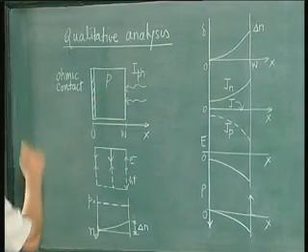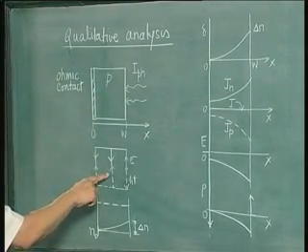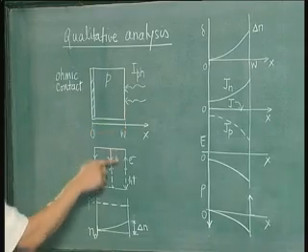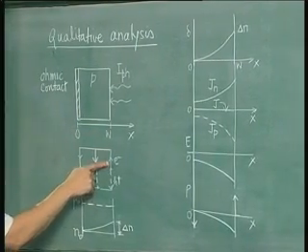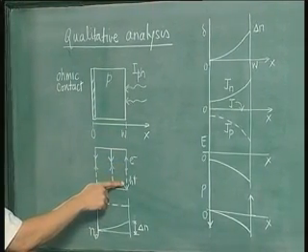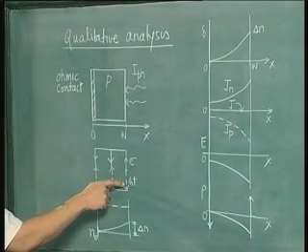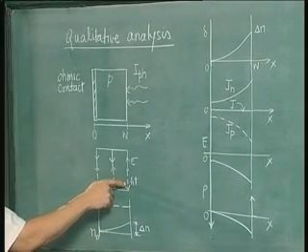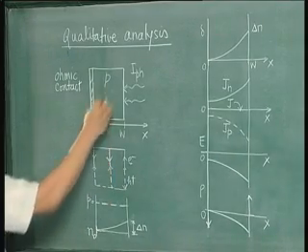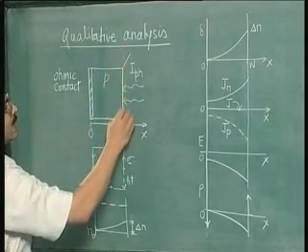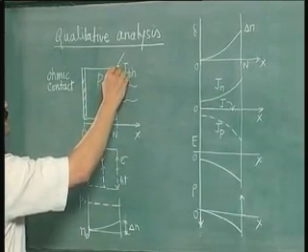The situation in the sample is depicted in this flow diagram. On this face here you have electrons and holes being generated. This is surface generation, that is, the unit of generation is per centimeter square per second. So per unit area of the surface, where area of the surface is in that direction. So that is the area we are talking about.